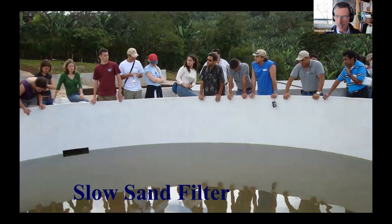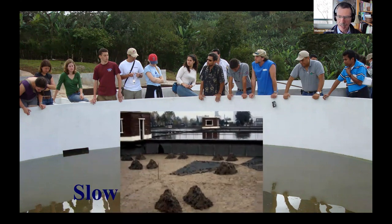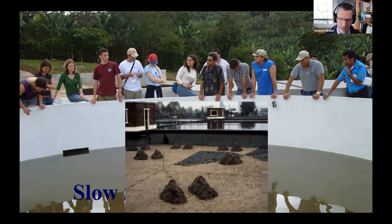And here's a slow sand filter built in Honduras. That was one of the student trips to Honduras. We're looking at the edge of one of the tanks. Here's a picture of a slow sand filter, and I'm guessing that this one might be in the United Kingdom. They're showing that workers were out on this filter scraping up the piles of Schmutzdeck. They've got several different piles there, and they also have one section here that they haven't shoveled up yet. So you can see the black slimy layer that was on top of the sand that they're removing.